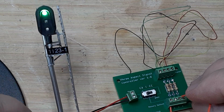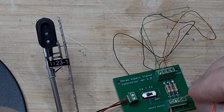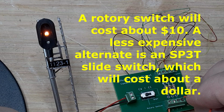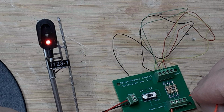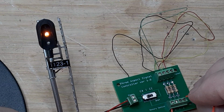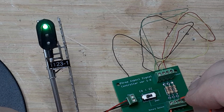There are 2 advantages to this control method. First, it's inexpensive. Including a rotary switch, you'll spend less than $20 to control a signal. Most commercial controllers will cost $40 or more. Second, since the switch is a mechanical device, it remains in position when you power your layout down, and when you restore power, all signals will display the aspect from the previous operating session. Many, if not most, commercial signal controllers initialize to a default aspect, requiring you to reset the aspects of all your signals when you power up your layout.